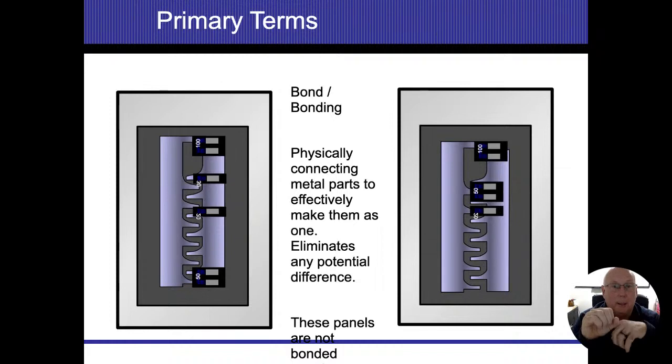So that if any wire comes loose, it's going to energize the case. I guess I should back up and make up a make-believe object. Let's say we have an electric dryer. That electric dryer has wires that are built into it. If one of those wires that energizes the motors comes loose in there and falls and touches the case, the metal container of that dryer, it's going to energize the case of that dryer. Even if a wire gets stripped free of the insulation and rubs on the dryer, that's also going to energize the dryer.